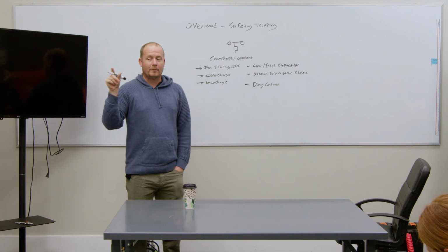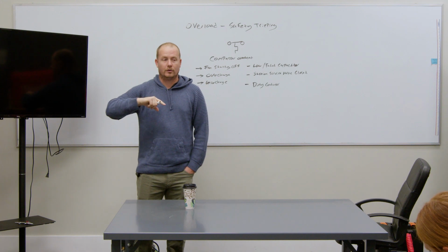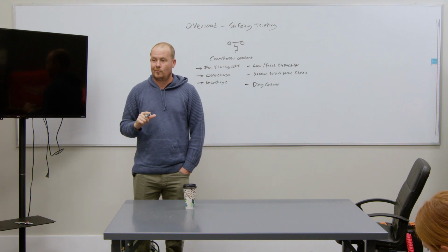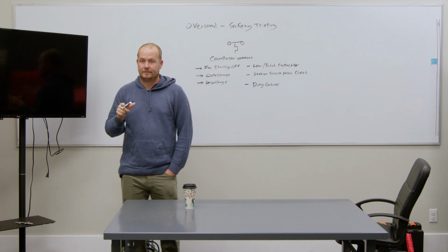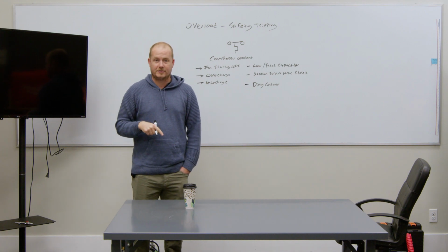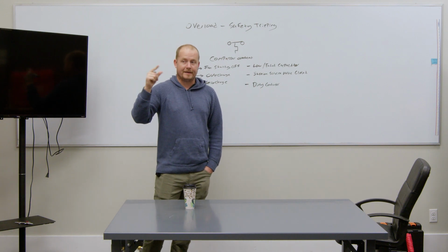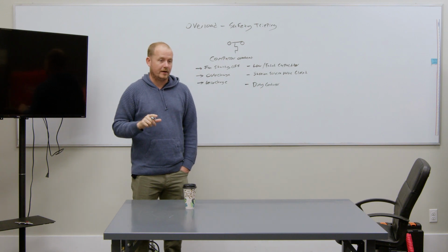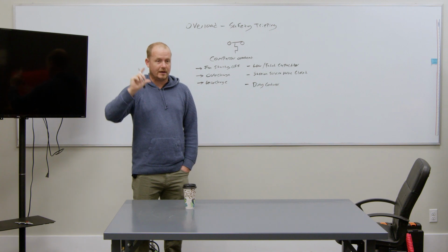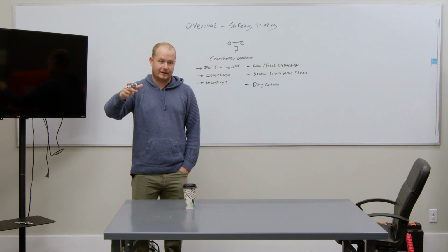So is there a case where you could have a compressor out on thermal overload where neither would be running? Yes. And what would that be? If you have a fan motor that's not running, and that's the reason why the compressor is overheated. So there are cases where you're going to walk up on a unit, the fan motor will be off, the compressor will be off, but the compressor's off because the fan motor's off. The thermal overload in the compressor is tripped because you don't have a condenser fan.